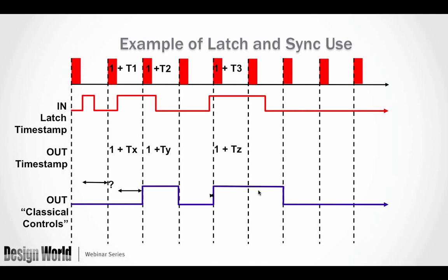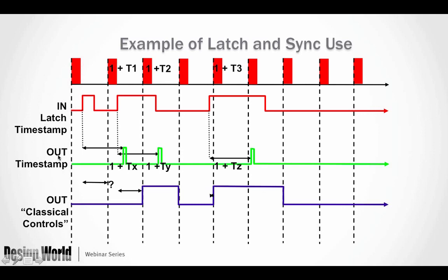With a timestamp input, we can grab these times that things actually occurred. So in this example, we're using the rising edge, but you can use both the rising and falling, or just the falling. And we can command an output with timestamp to execute a command with a fixed constant value after we saw that input. So this reaction to the input could be just a fixed constant, or it could be a constant based on, for instance, the conveyor speed of your system, where you're calculating how far down your cutter or your rejection device is for your bad product.